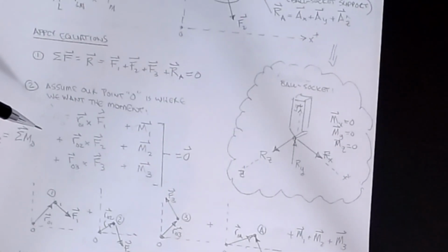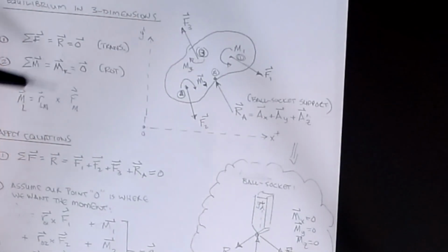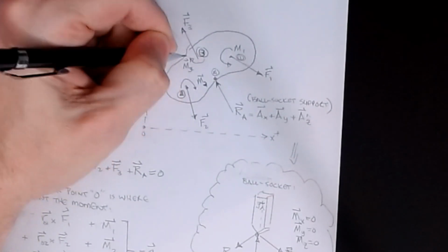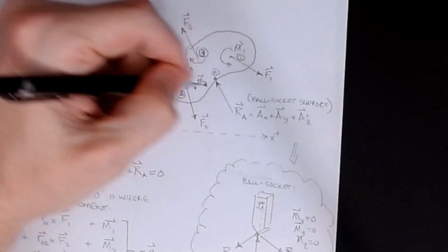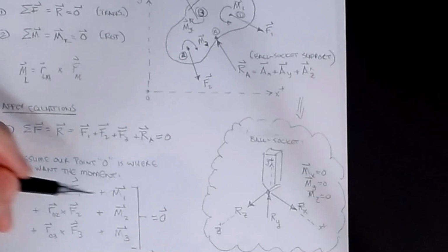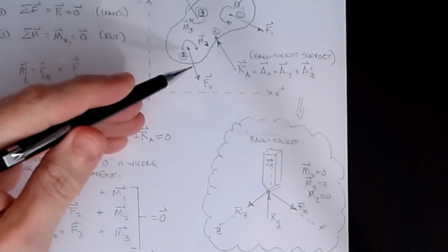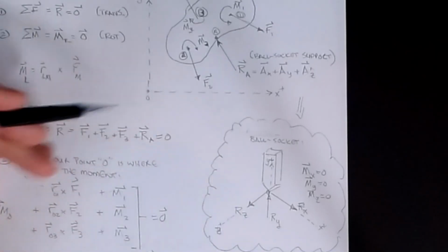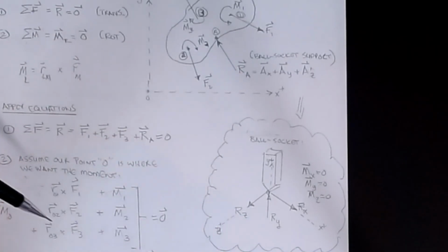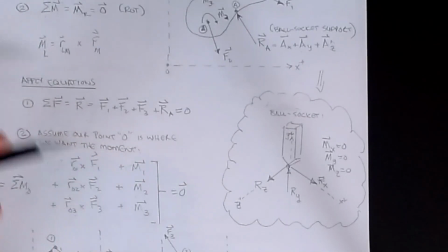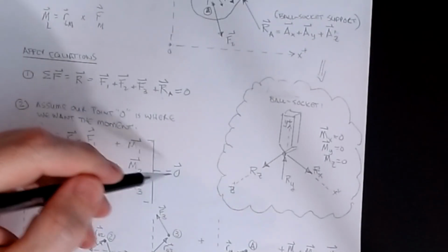And then the other piece that's on here that hadn't been included before is I also have these concentrated moment vectors. That needs a hat. And M2 does have a hat. Okay, so those are vectors. And for those, remember, moments are free vectors. So they already have the units that you want. They're already moments, and we just add them explicitly to the object. So all I'm going to do is add M1, add M2, add M3, and this whole thing, and it's a bit of a long equation, is all going to be equal to 0.